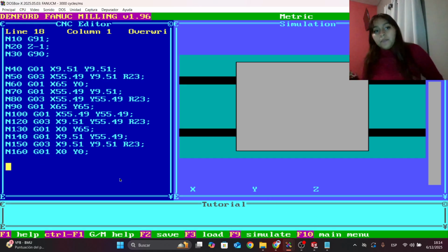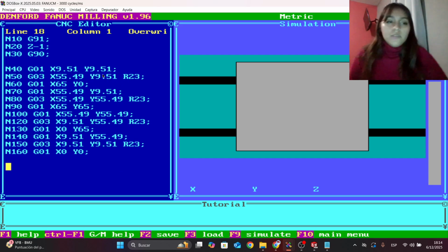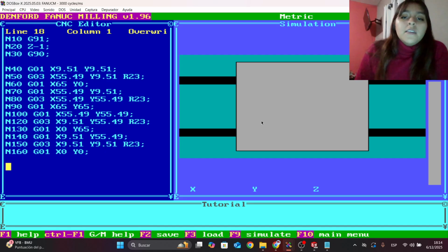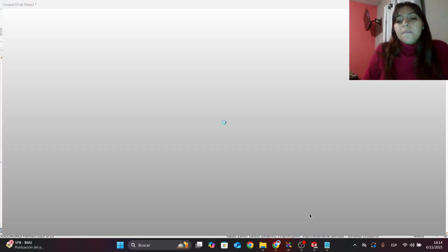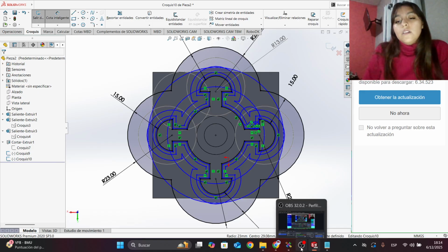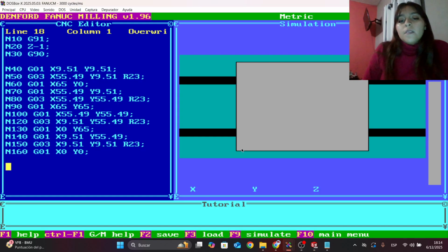And an important part, let's just go over the movements again. We start here, and we go from that part. Yes, because I use G03, so we go anti-clockwise. So we start from the lower circle, like here. We do this, and we continue that way. We start here, we go to the first coordinates with the G01, and then we go G03, and again.